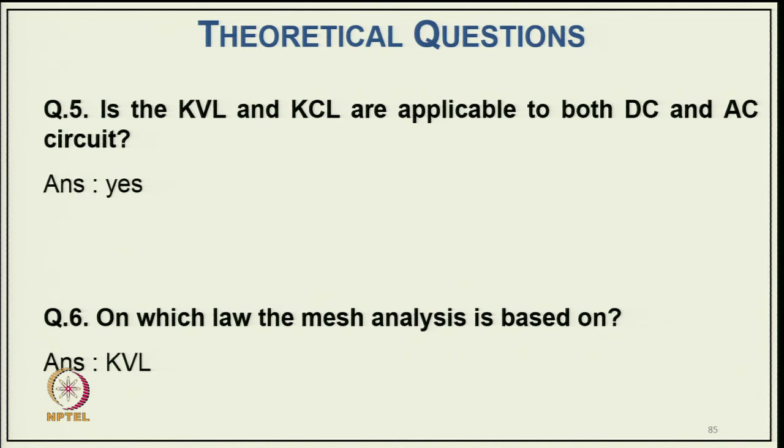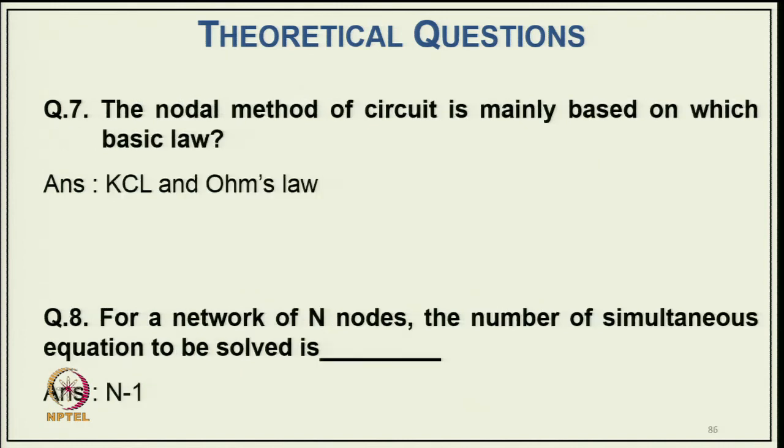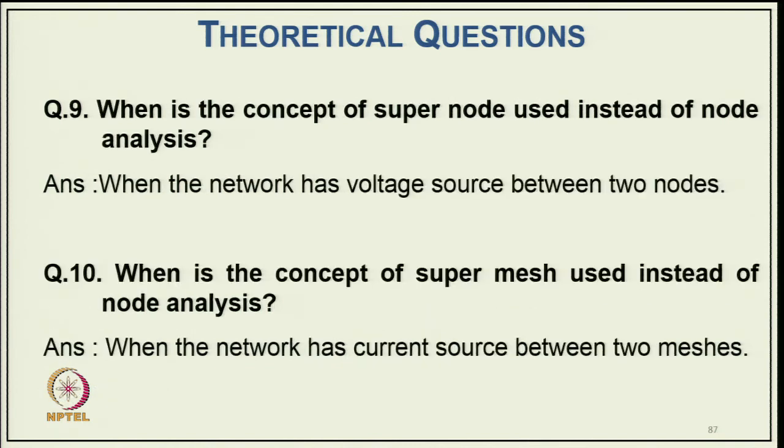On which law is mesh analysis based? Mesh analysis is based on Kirchhoff's voltage law. The nodal analysis of a circuit is mainly based on which laws? Kirchhoff's current law and Ohm's law. For a network of n nodes, the number of simultaneous equations to be solved is n minus 1, because one node is the reference node or ground node.